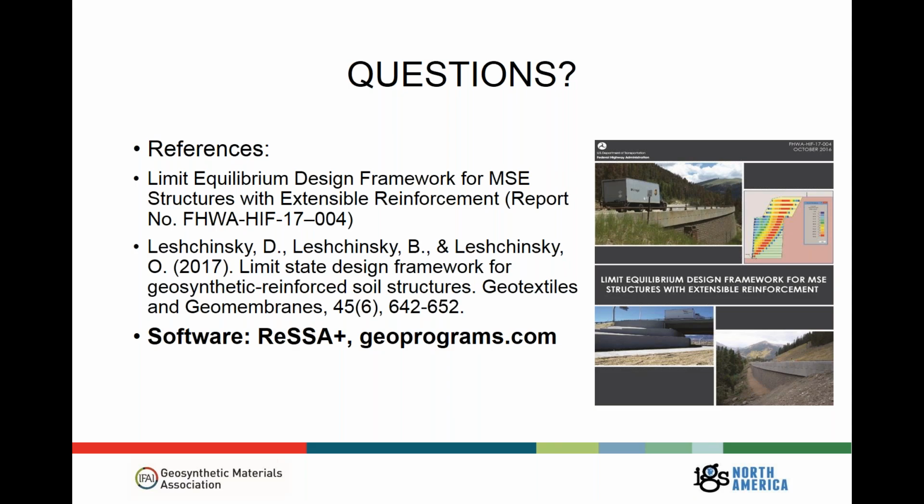So it comes down to a construction issue, it comes down to a serviceability issue, and as I mentioned at the beginning, we hope, and it's been shown generally, that sufficient strength limit state design will give us at least some confidence that we'll probably meet serviceability criteria as well, which we're much worse at actually capturing without complex numerical models.